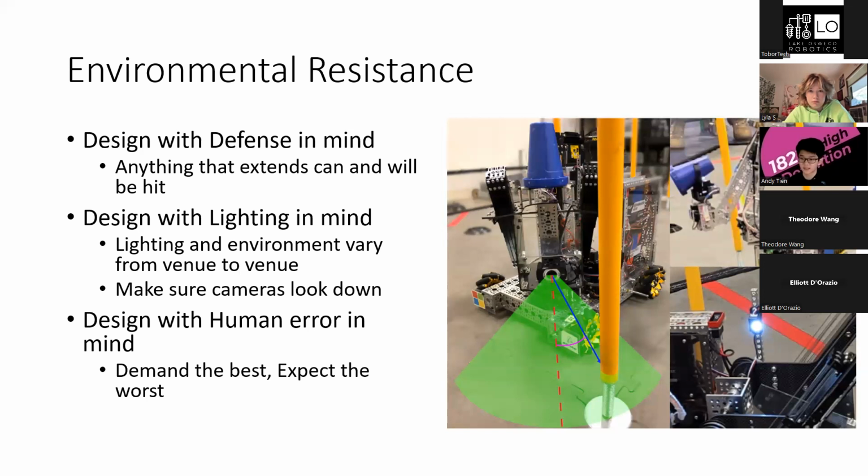So when designing a robot, you have to consider how much error your drive team can have before your robot stops becoming as efficient. And that was the big shift in design philosophy that we experienced, going from states to worlds, was that our robot became a lot more driver tolerant. So we had around 7 inches of tolerance both in the intake and the outtake.